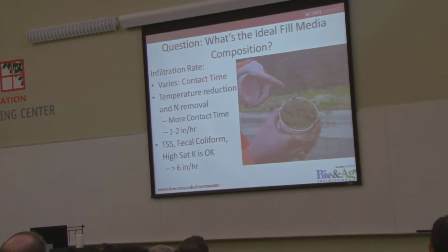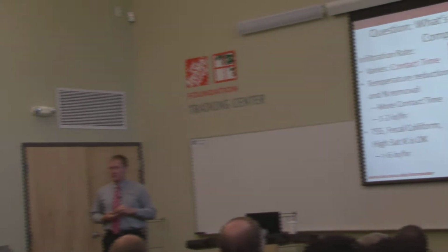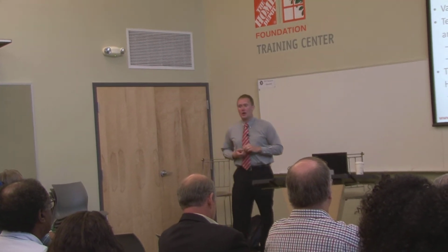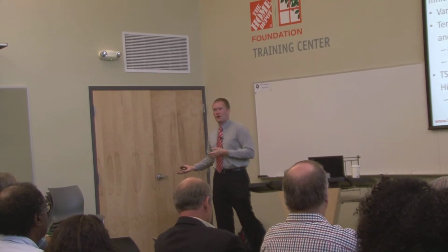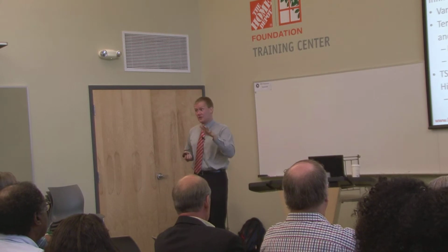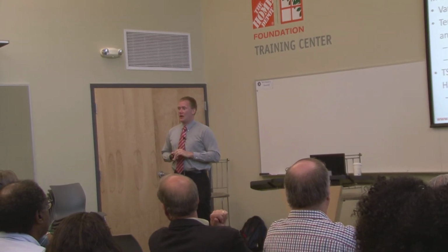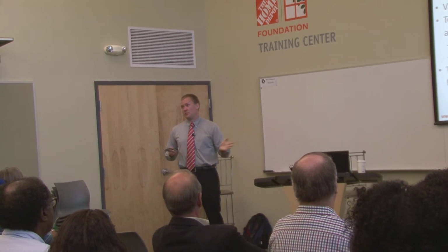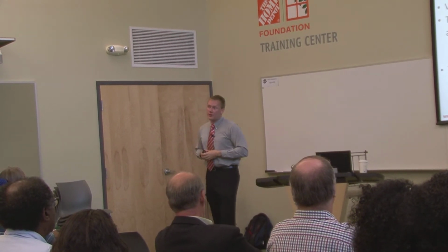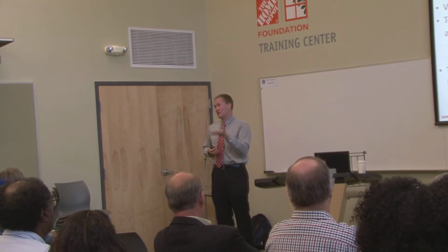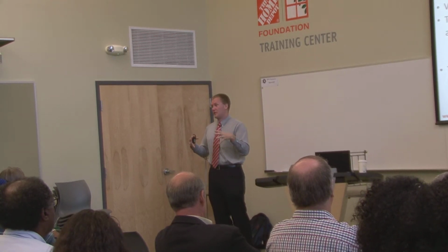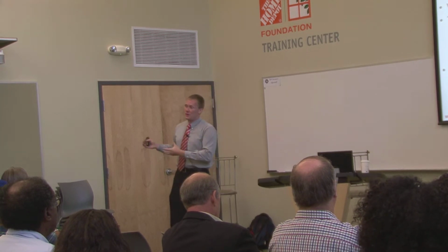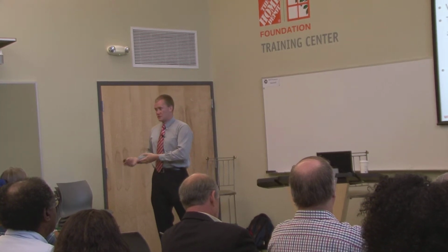So if you have cold water fisheries or cold water habitat, which you do in the northeast part of the state, trout and salmon species basically are killed off when water temperature gets above 70 or 75 degrees Fahrenheit. And so of course the runoff coming off of the parking lot outside the building here could be 100 or more degrees Fahrenheit. And so if you can get some temperature mitigation in your bioretention cell before the water gets transmitted to the stream, then you're going to do less impact on those trout streams.